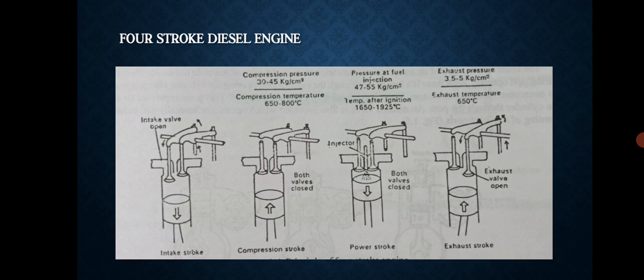In a 4-stroke cycle engine, there are 4 strokes completing 2 revolutions of the crankshaft. These are respectively the suction, compression, power and exhaust stroke. In the figure, the piston is shown descending on its suction stroke. Only pure air is drawn into the cylinder during this stroke through the inlet valve, whereas the exhaust valve is closed. This valve can be operated by the cam, push rod and rocker arm.